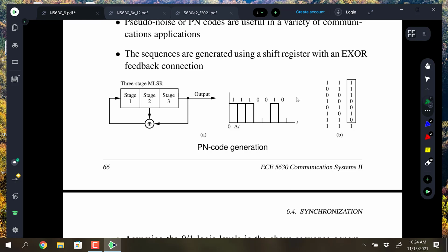Yep. So that's what's good about the Gold code. They can all be the same length, 1023, but the codes are different so that you can use them for multiple access communications, and that's what GPS does. GPS is a multiple access system where each satellite has its own Gold code, and that's how it's separated from another signal. And the Gold codes let you do that at the coarse acquisition level.